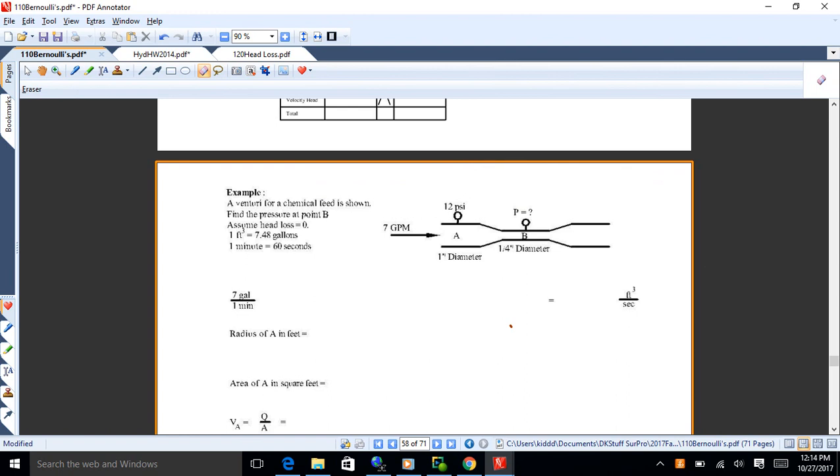Yeah, 27.7. So yeah, just get that converted. So 12 psi. And just remember the proper conversion to use on these things, that you got things on the proper side of the fraction and all that. Remember what 12 psi is, 1 over 1. So the psi will go on the bottom. So what you got here is 1 psi will get you 2.31 feet. So that's going to come out to be 27.7. I took this out of this because these numbers get a little fine. So I made it 7 too. It might be overkill, but I guess it can't hurt.